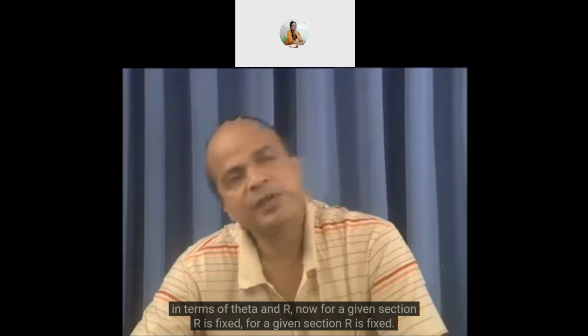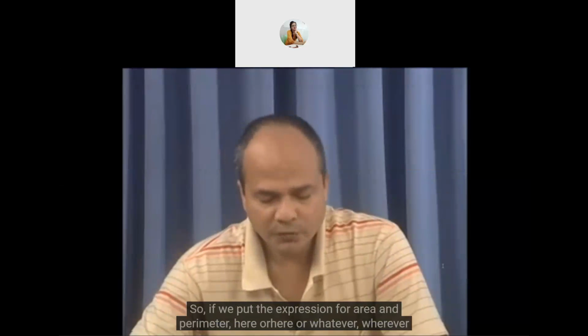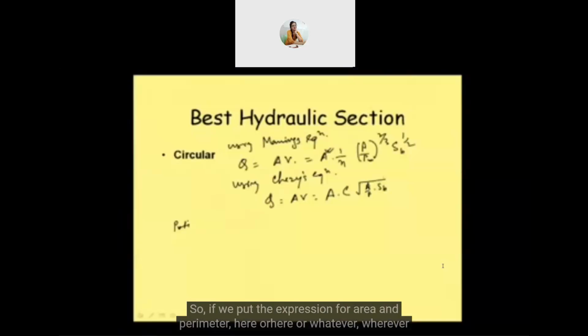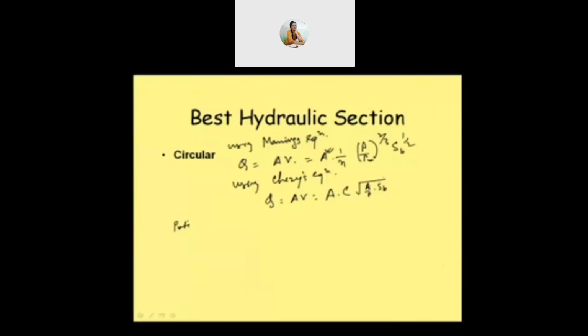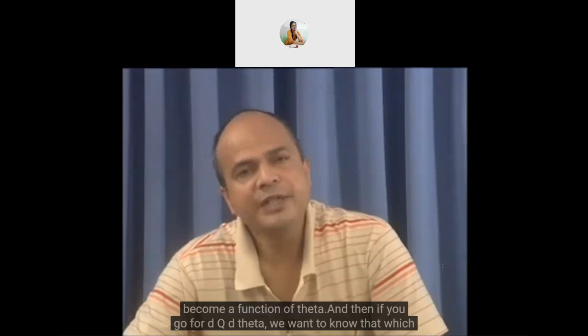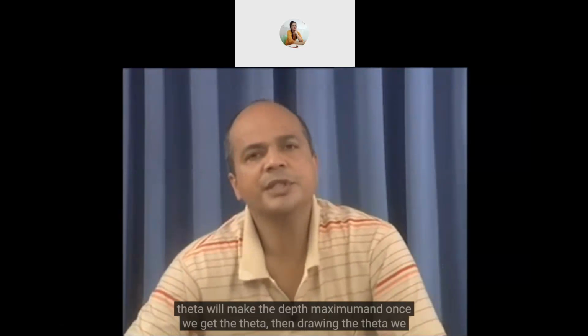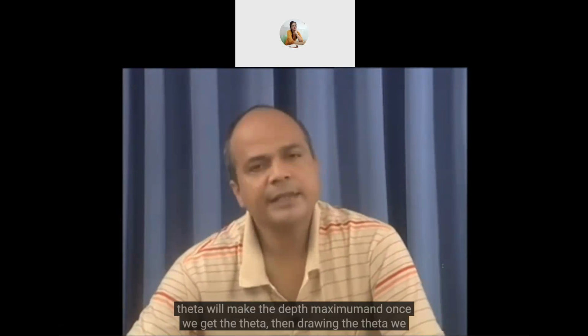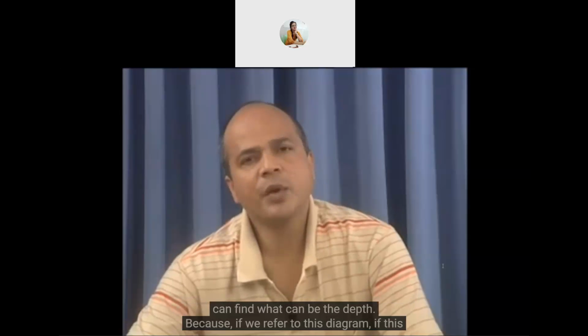So if we put the expressions for area and perimeter here, wherever it is, we'll have the expression for Q in terms of theta. It will become a function of theta. And then if we go for dQ d theta, we want to know which theta will make the discharge maximum. And once we get the theta, we can find what the depth can be.